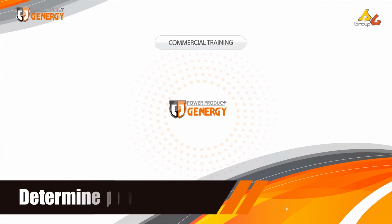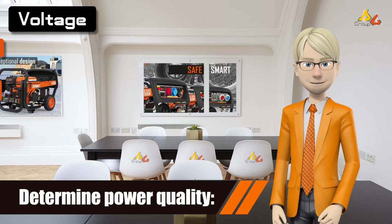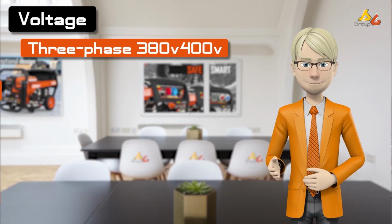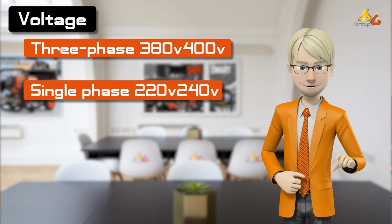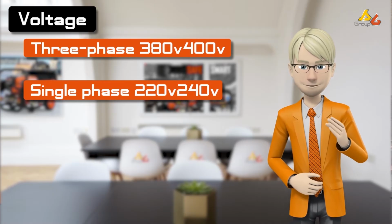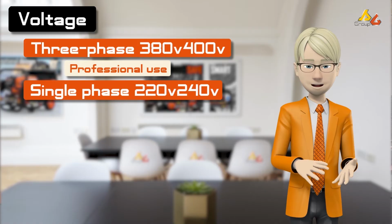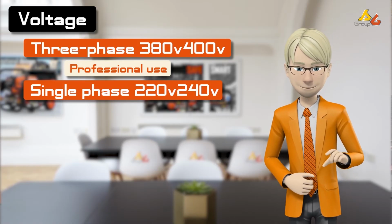Determine power quality. Voltage. In Spain, we will use two types of voltages, three-phase and single-phase. Three-phase 380 to 400 volt units are normally reserved for high power and industrial equipment, intended for professional or business customers, and to connect to large motors, machines, or pumps.